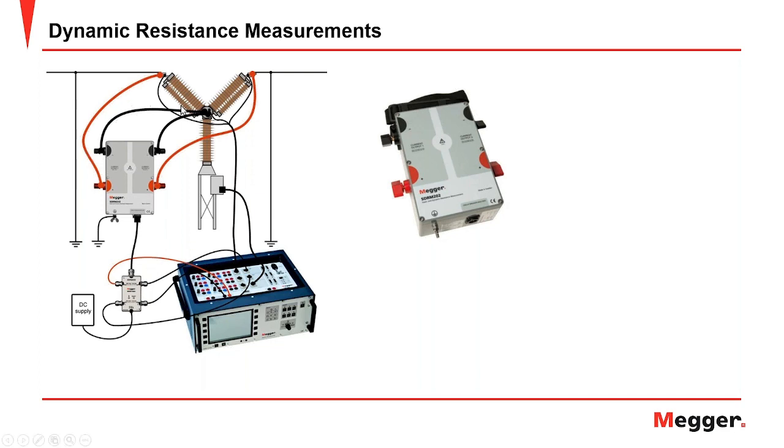So current injected across each break per phase. So in this case, this is one phase, 2 breaks per phase in one current supply. And of course, the circuit breaker analyzer will trigger the current injection and perform a measurement of the current and the voltage drop across the contact during the test.